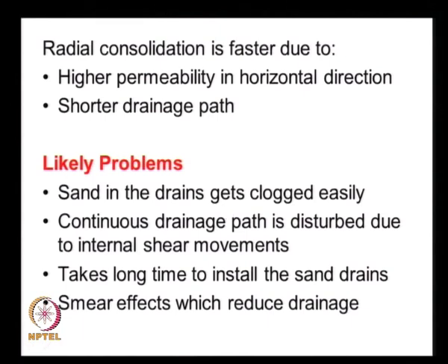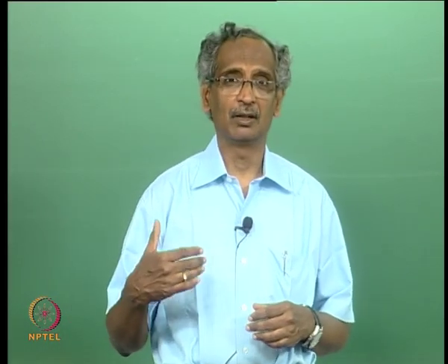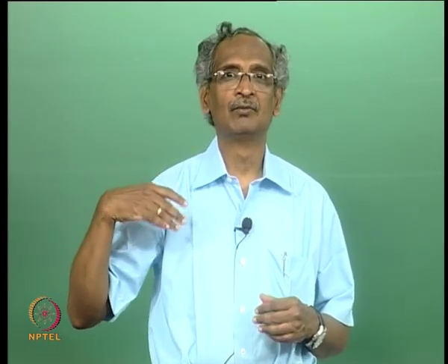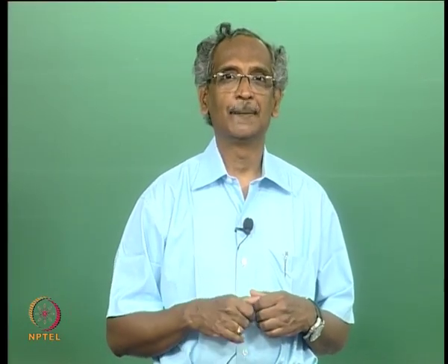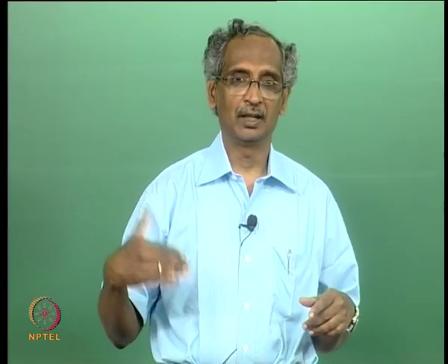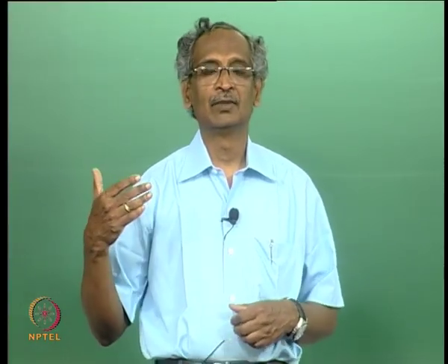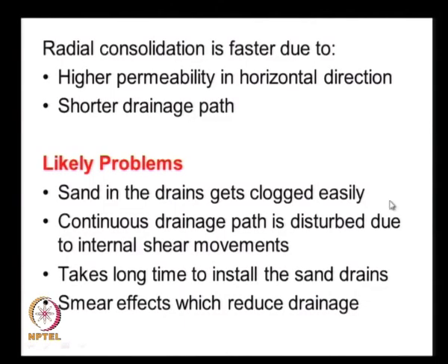thereby impairing the permeability of the sand, and then the continuous drainage path may be disturbed because of internal shear deformations, because all these pre-consolidations are achieved by constructing a surcharge, and if we are not careful enough in applying a uniform pressure and applying the surcharge load at a slow enough rate, there could be large lateral deformations or shear deformations, and because of these shear deformations the sand columns may undergo some distortion, and in that case the flow path is disturbed, and once the flow path is disturbed, that particular sand column becomes ineffective, it cannot transmit any water,